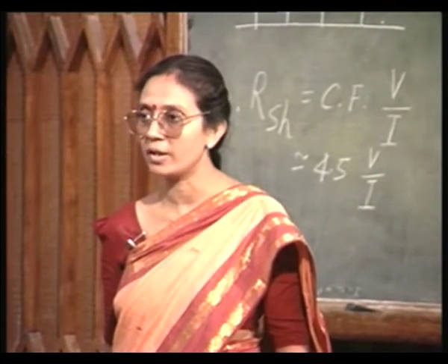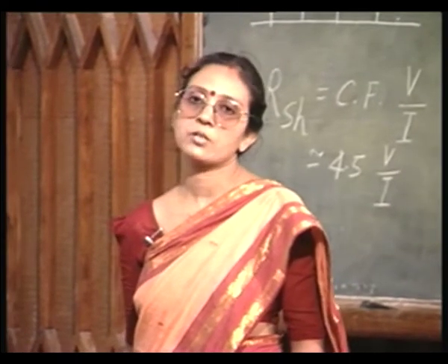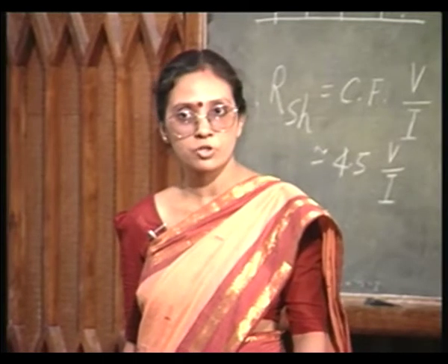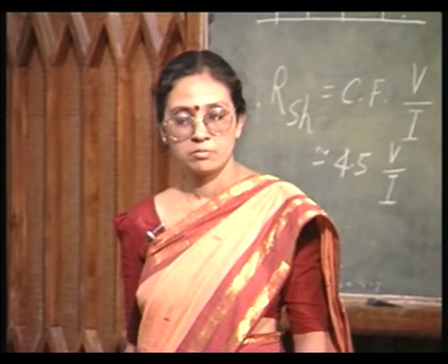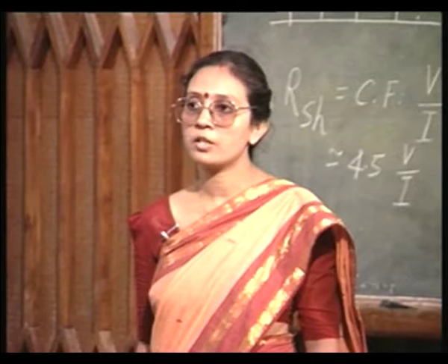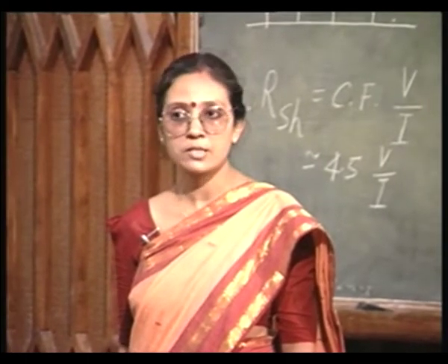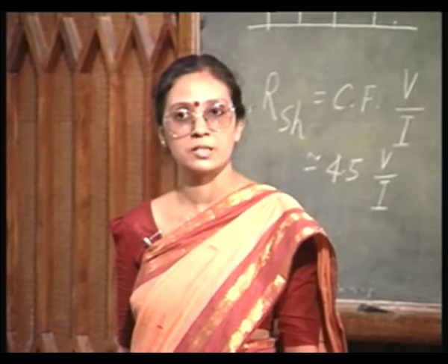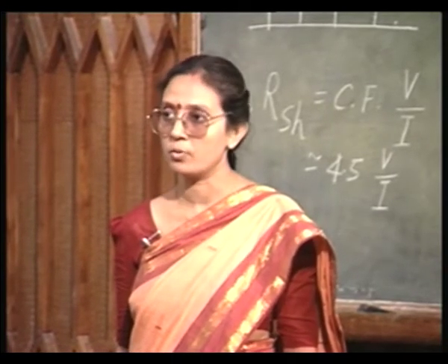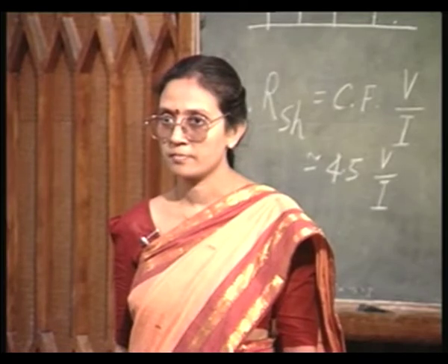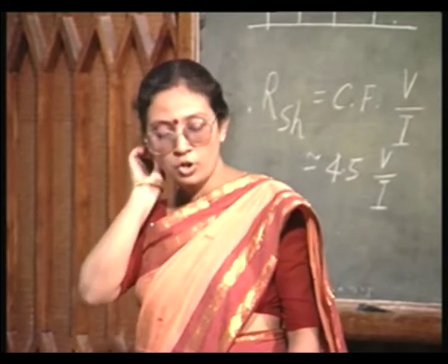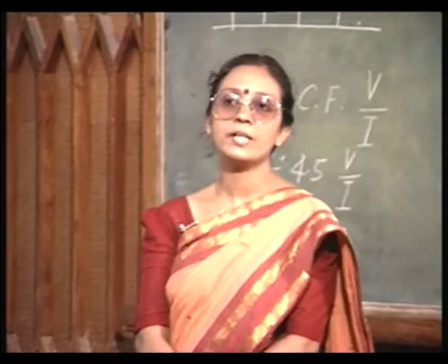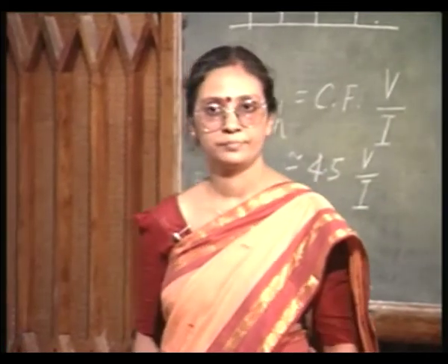How do I verify? And you already know, like in the case of phosphorus diffused in silicon, the doping profile does not really match Gaussian. Okay? For boron implantation in silicon, you know it does not really match Gaussian, it is a Pearson 4 type distribution. So, how do I know these things? How did people find out these things? Which brings me to the question of how does one find the doping profile?